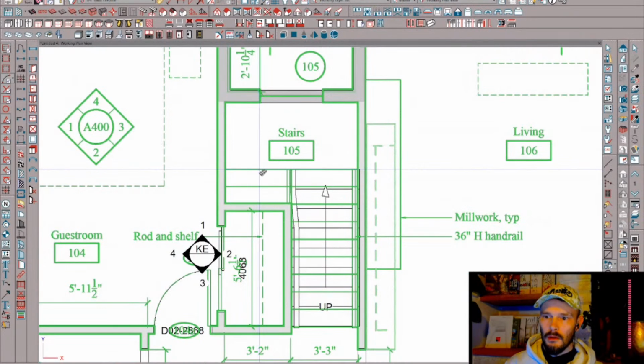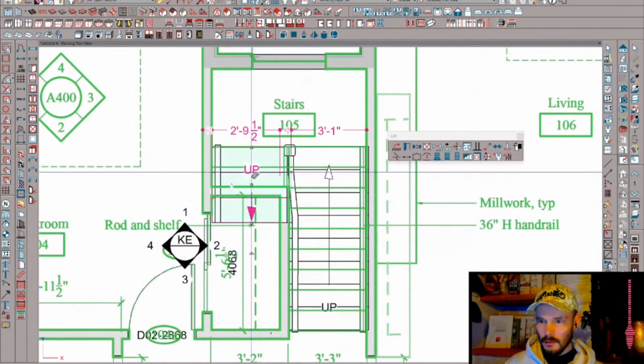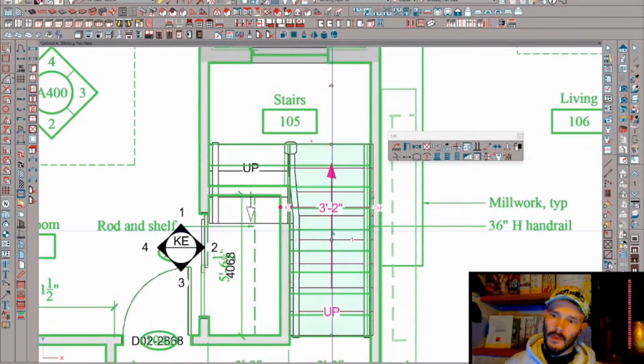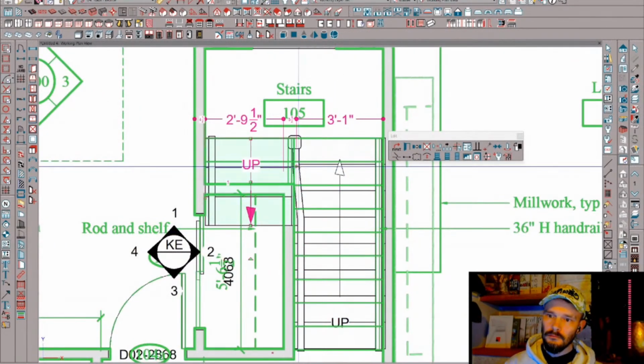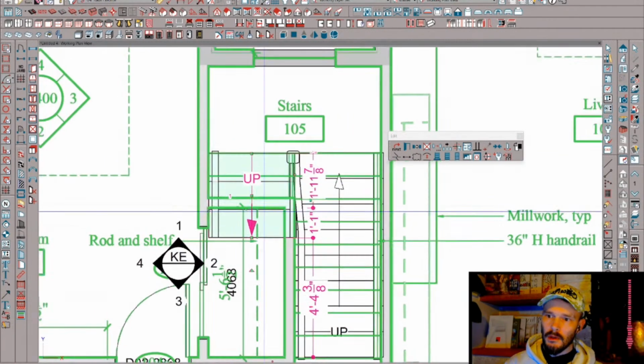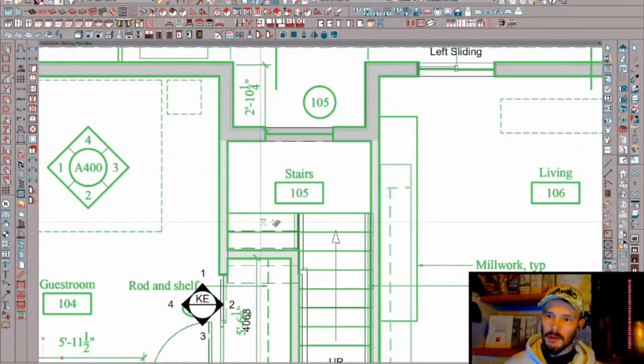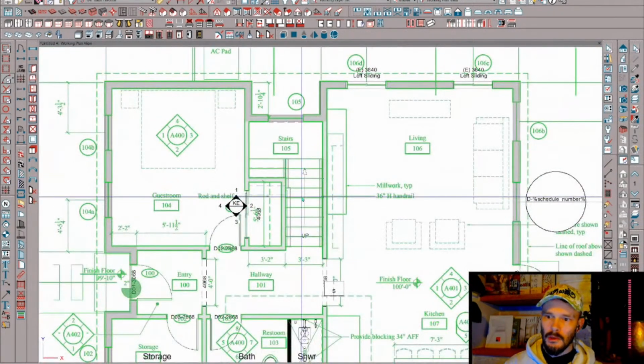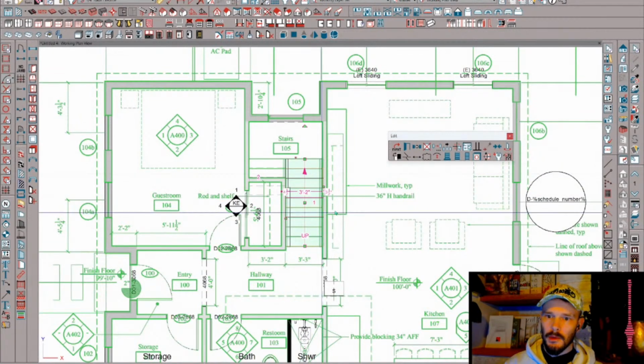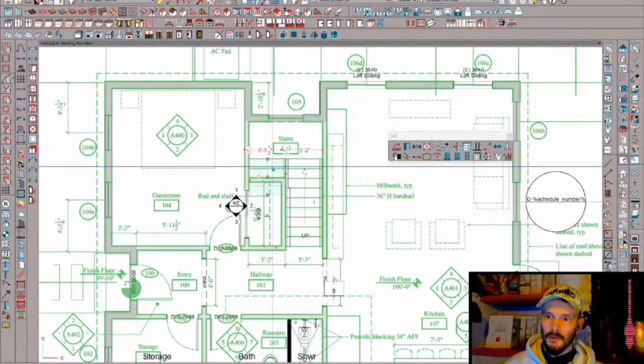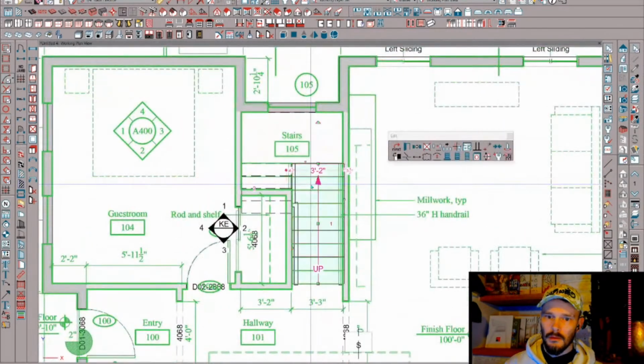And then we've got, so depending on the height of this, I could probably figure out what these stairs are. But in the meantime, what's the distance here? 3'2", and this is not wide enough. What's going on there? That's odd. That's very odd. Okay, maybe it's existing space. Click in between and we get a landing. And then we can just populate this. Hopefully that made it to the stairs above. Right? Did that? Yeah, it did. Okay.